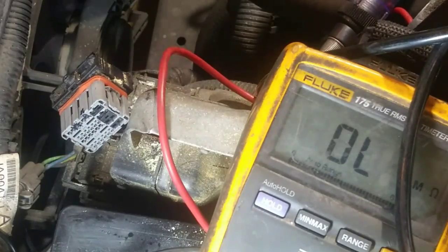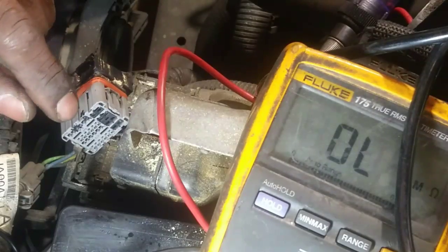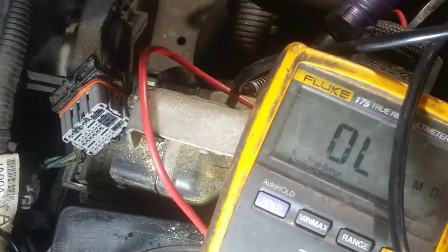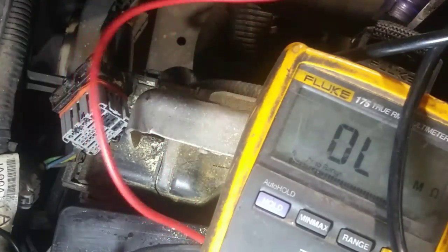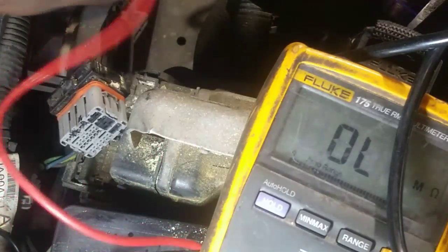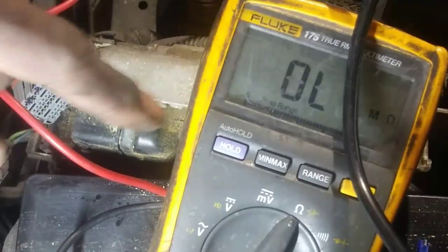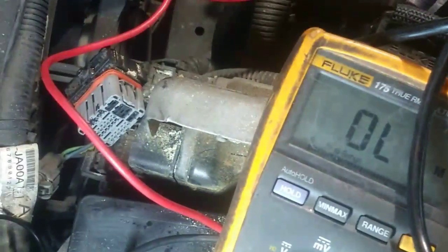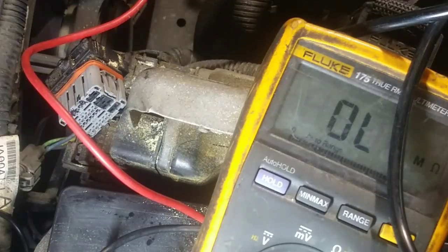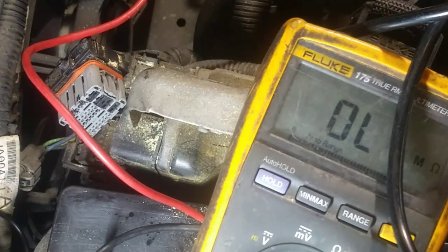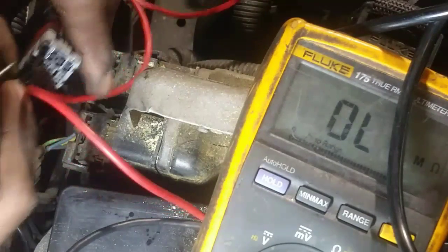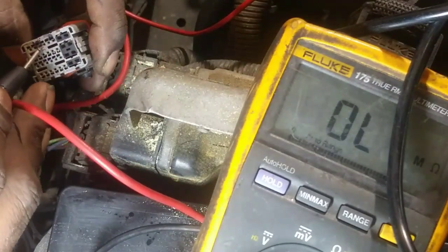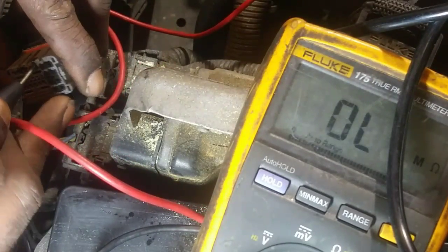Now what I'm going to do is a resistance test from here to the wire there. So we're going to connect our multimeter that's back hooked up to the alligator clamp there. And then we're going to do a resistance value test from there to there, from here to there. So it should be very low ohms.